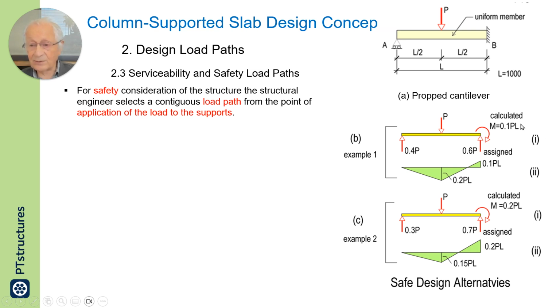The calculated bending moment based on the elastic response was different. But this is the selection of the structural engineer. Here, another engineer assumes the moment to be 0.2 PL. Then, based on this assumption, we use statics and calculate the reactions. The reactions are different.